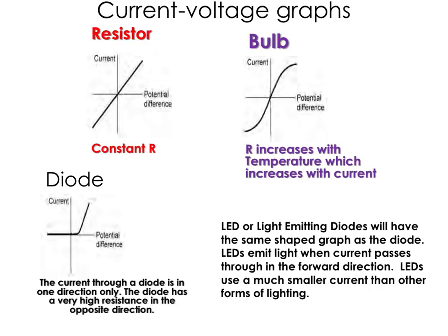Diodes have a very interesting graph. Remember that a diode only allows current to flow in one direction because you've got a very high resistance in the backwards direction. So you get no current at all in the backwards direction. And then in the forwards direction, it would take a while for it to begin, but then you get a spike in current. And then again, you can see it increases at a linear rate.